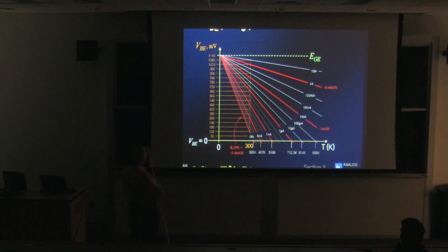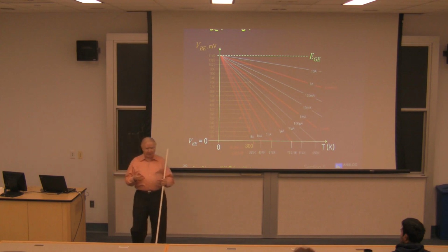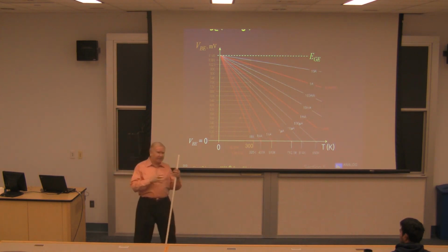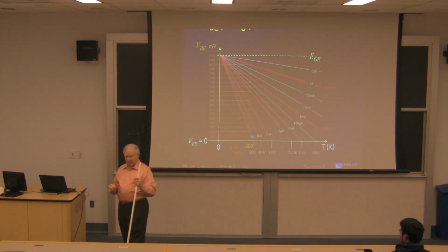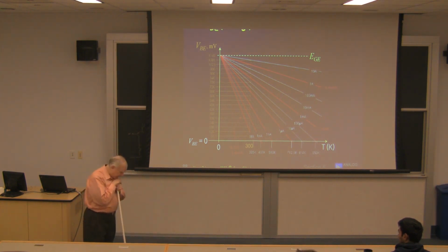Well, I didn't mention this, I should have done, but all of these curves converge on the band gap, which for this particular device is about 1.14 volts. The band gap is a little bit less in practice than in theory. Theory says it should be 1.206 because of a number of factors. The doping lowers the band gap energy. You can see why that is because you're disrupting the lattice, and that's going to make carriers more likely to be available, more vacancies will be generated.